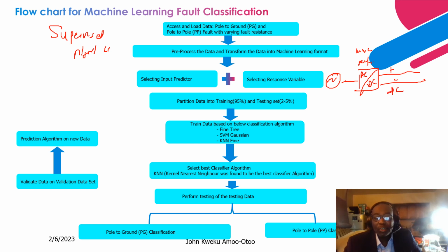For the DC transmission section, it then goes to an offshore converter, another MMC converter, that basically inverts. So this is an inverter, this is a rectifier, and it inverts the DC to an AC equivalent, and from there it is integrated into an AC grid.